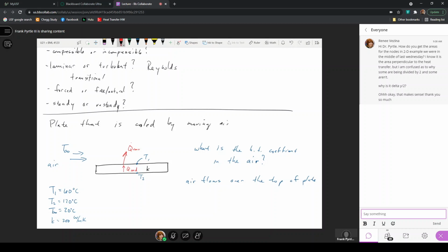So here, the heat that is moving away from that surface must be equal to the heat that's moving to that surface. The heat transfer rate by convection will be h times (T1 minus T infinity), because that's the surface that's exposed for convection, times A.